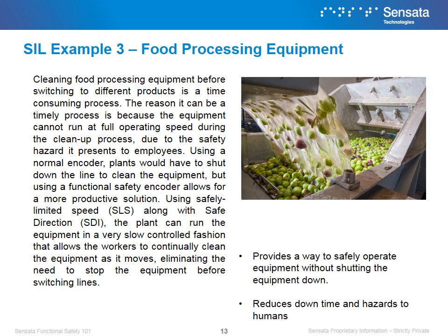Using safely limited speed, SLS, along with safe direction, SDI, the plant can run the equipment in a very slow, controlled fashion that allows the workers to continually clean the equipment as it moves, eliminating the need to stop the equipment before switching lines.